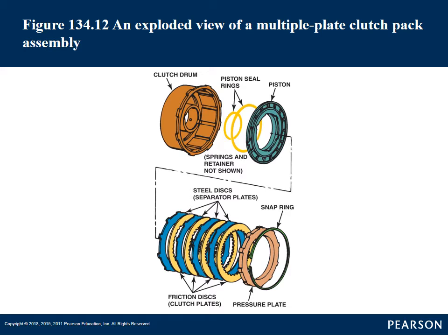Then you'll put your clutch packs in, your backing plate, and then your snap ring, the big snap ring on the outer side. That's what holds your different clutch discs and your apply or backing plate in the drum. But there will be a different snap ring, not listed here, that holds the spring and piston assemblies in the drum also.